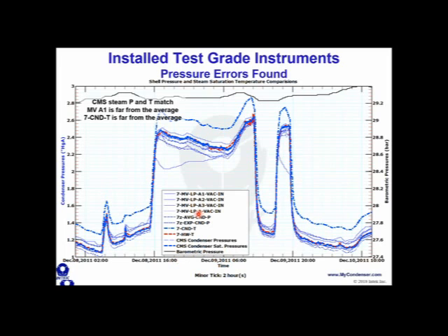So when you validate measurements, use what you have. Grab steam temperatures and all the steam pressures, turbine exhaust pressures, grab all the pressures and temperatures you have access to, and do a comparison just like this. So these three are their independent vacuum measurements. They have 3 independent pressure transducers monitoring condenser pressure. They're all very good quality instruments, but they are not installed properly.